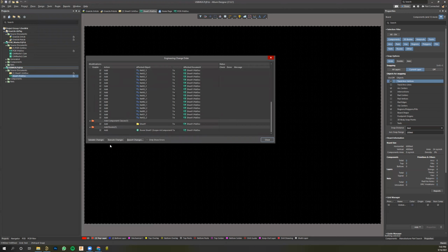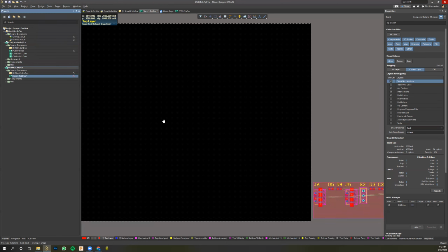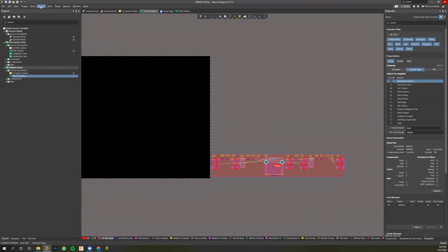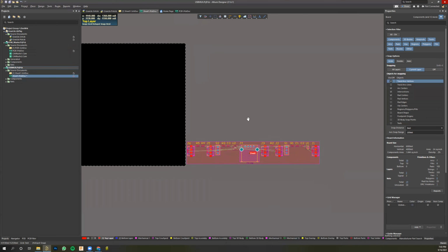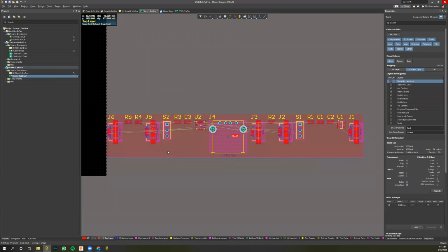When it says, well, I'll leave the room in, but just know that I'm going to show you what a room is. You can uncheck it whenever you do this process. I find them irritating. But I'm going to leave it in so I can show you what it is. Validate. Everybody's happy. Execute. And then off to the side, it'll pull in all your parts. That was, by the way, design import changes from the PCB project. And so all of our parts came in, and this red thing is a room.